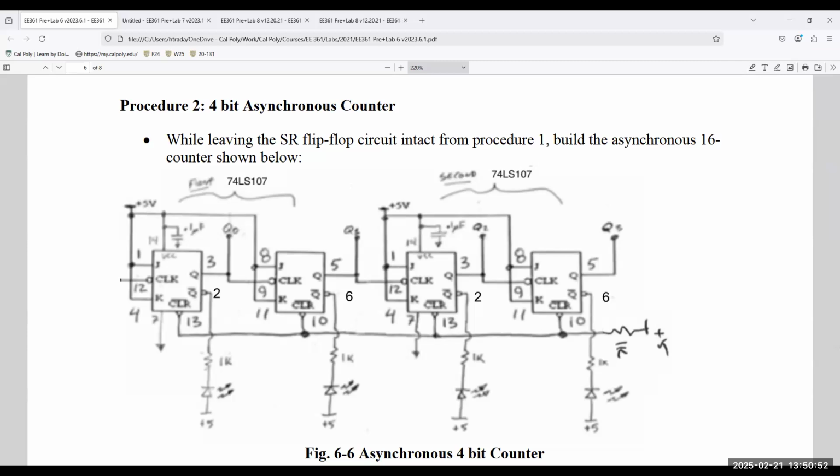But because it's 0, we connect the LED cathode to the output of the chip and not the anode. So the anode is held at +5 volts. When the output Q0 is 1, meaning Q is at 0, the LED should be off. So if Q0 goes 1, cathode is also 1, and anode is also 1, the LED turns off.